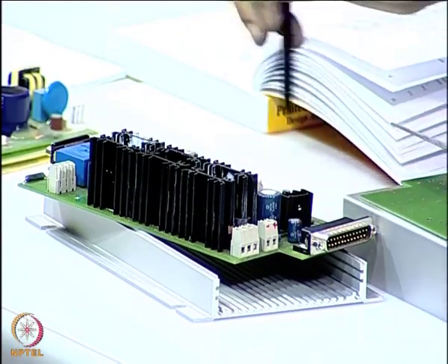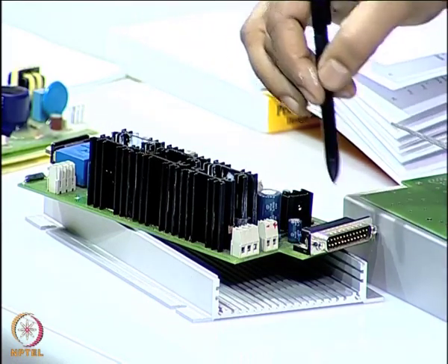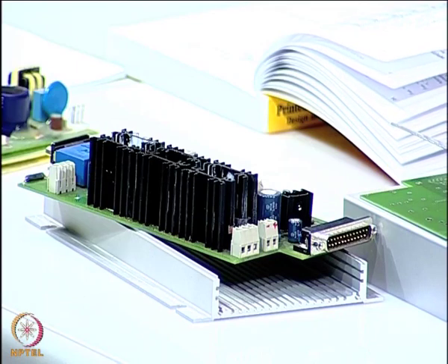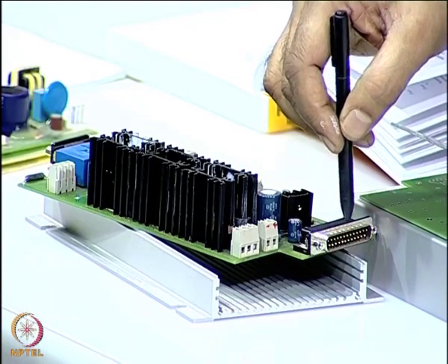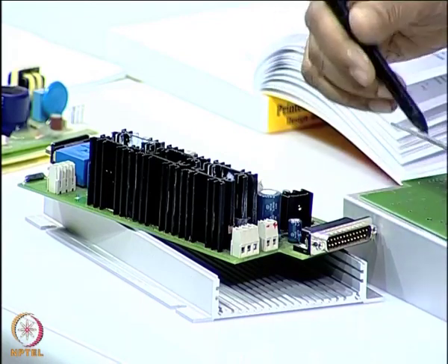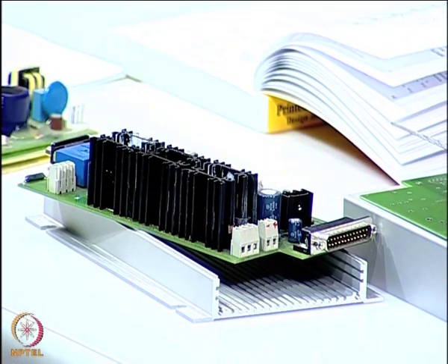So these occupy quite some amount of space in your printed wiring board, and these are the external links from the PCB, or this is where the internal circuit gets linked to the external world. So, the connectors should be placed according to how the external links, or where it connects, is decided. So, this is where some amount of discussion with the physical equipment designer also matters a lot.